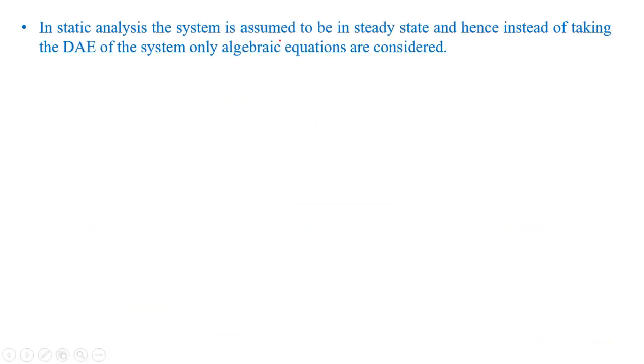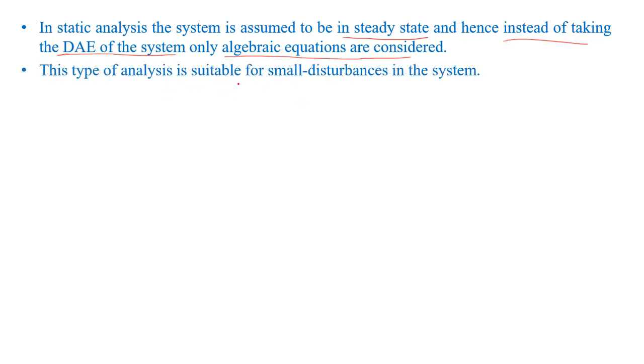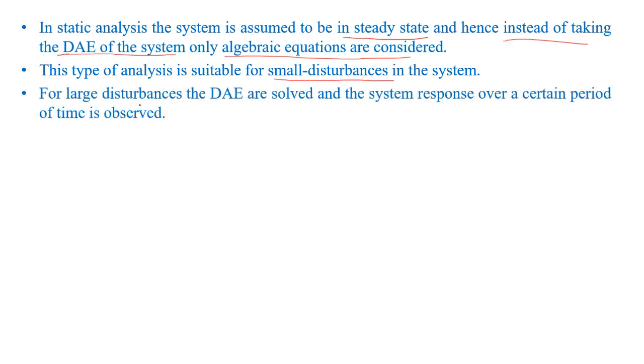In static analysis, the system is assumed to be in steady state, and hence instead of taking the DAE, the differential algebraic equations of the system, only the algebraic equations are considered. This type of analysis is suitable for small disturbances in the system. Whereas for large disturbances, the DAE are solved, and the system response over a certain period of time is observed.